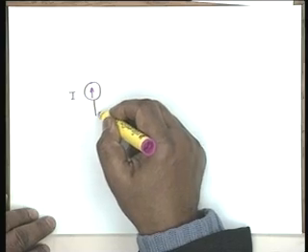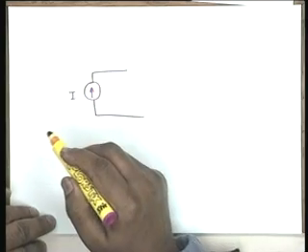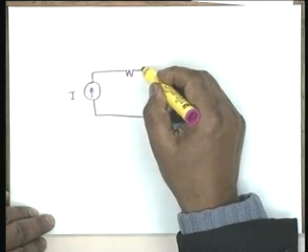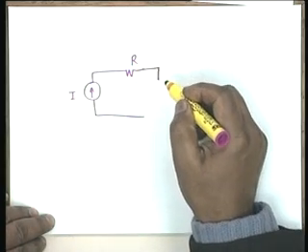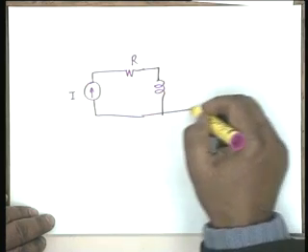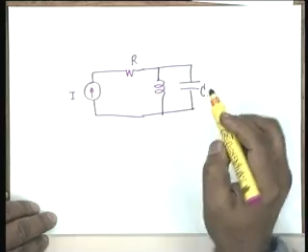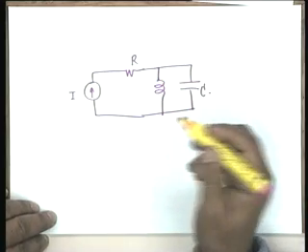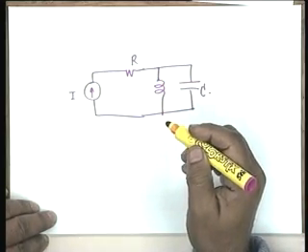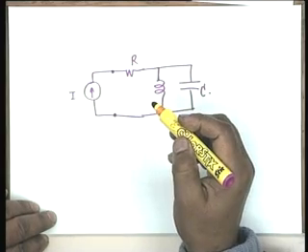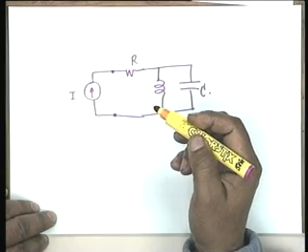All right. Let us take this example. I have a current generator I. Now I am drawing it in terms of the transforms, and since I am talking of network function, I am talking of initially relaxed elements, let us say I have R, L and C. Now obviously the driving point function, you are driving only at this port, so the driving point function can be either an impedance or admittance.